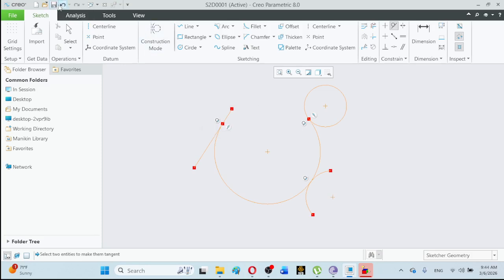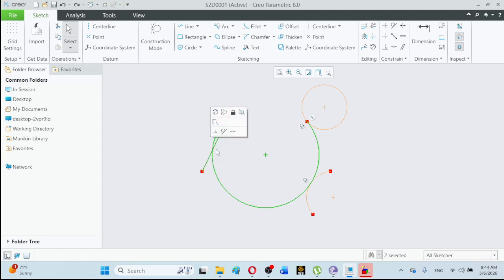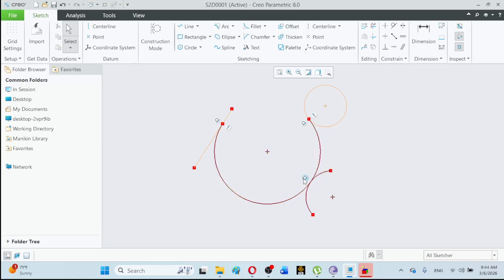Another way, as I had previously also explained, is to click on this circle, this entity and the other entity, and here in the side menu this tangent constraint has been listed, so it has been applied. So like this, these constraints can be controlled. So actually this tangent arc command can be used similar to the 3 tangent type of circle.